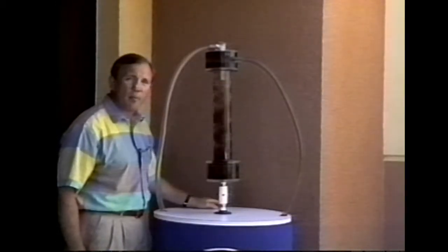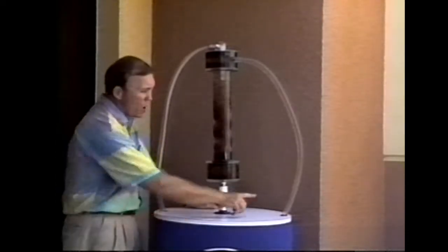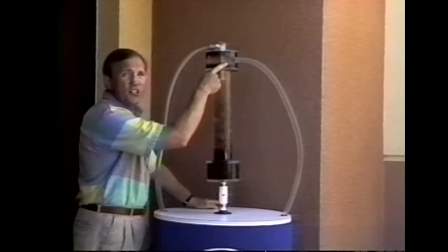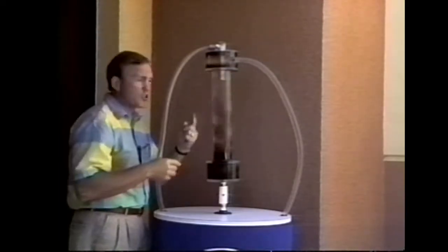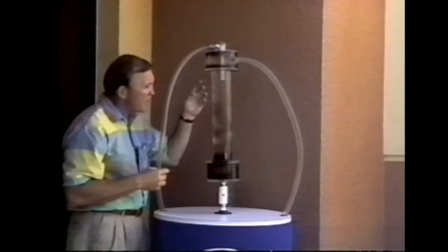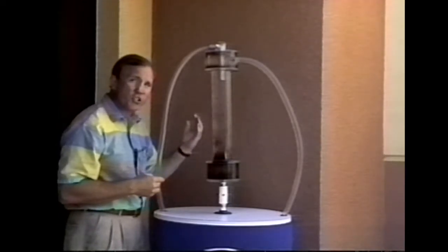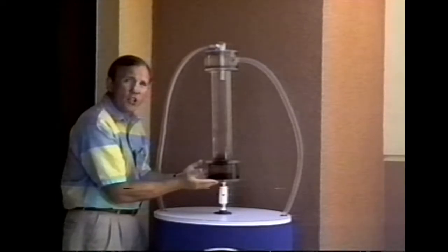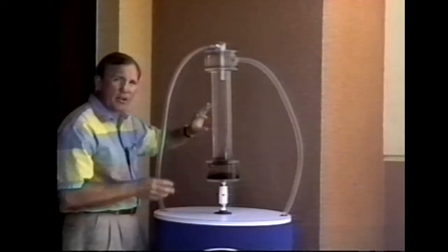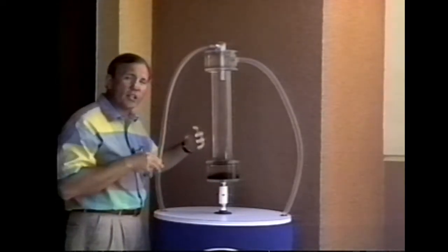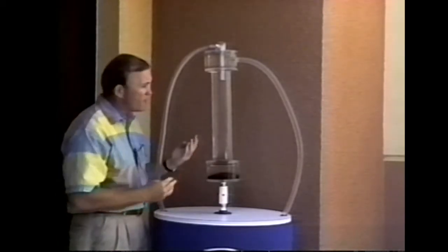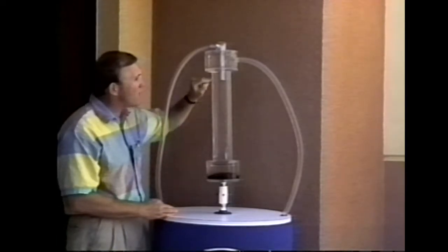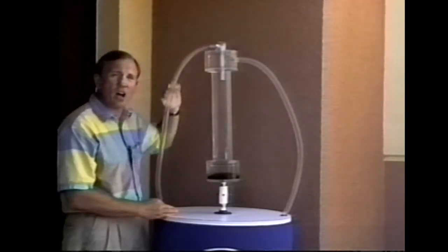The sand separator operates off centrifugal action. The water comes in on this pipe off the discharge of the pump, and enters the unit tangentially at the top here. The centrifugal action begins and moves that sand to the perimeter of this chamber. That sand then falls and collects in this lower chamber. Back up in this area, that outward centrifugal action creates a low-pressure vortex. That vortexing actually provides an outlet for the water, which discharges out this middle pipe,